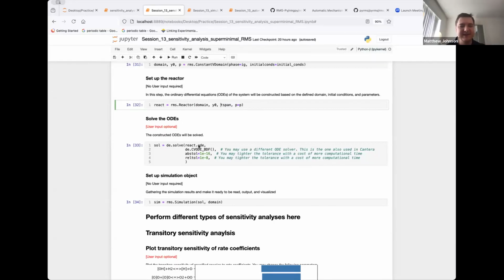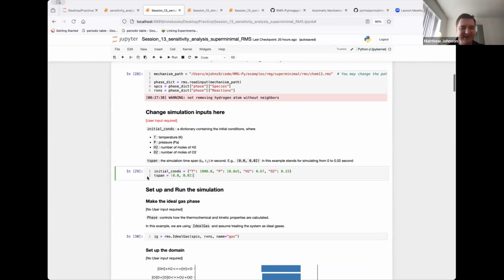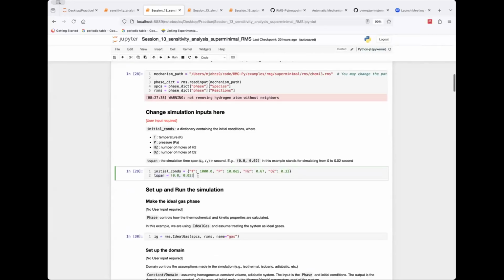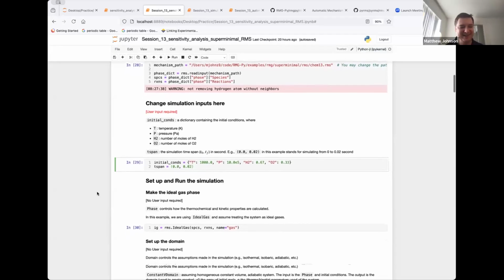So this simulation was run for a specific time span here. You just chose to do it at the end? If someone's doing an ignition delay or something, then at the end everything's just exhaust gas. I would suggest just running it once, figuring out how long to run it, and then simulating it again, which usually isn't going to take very long.